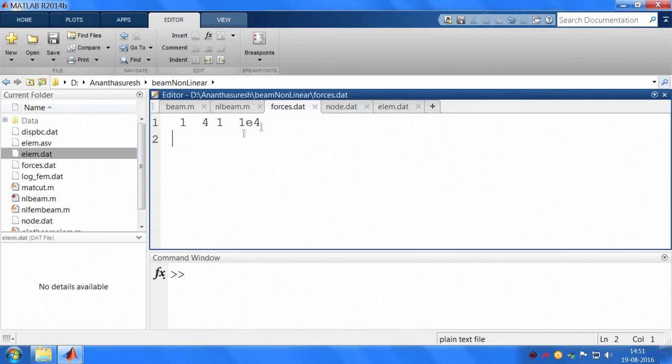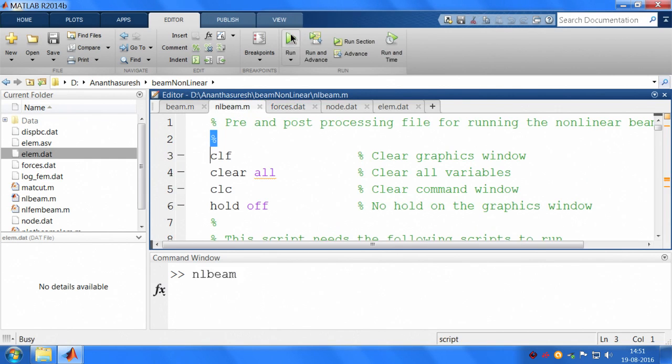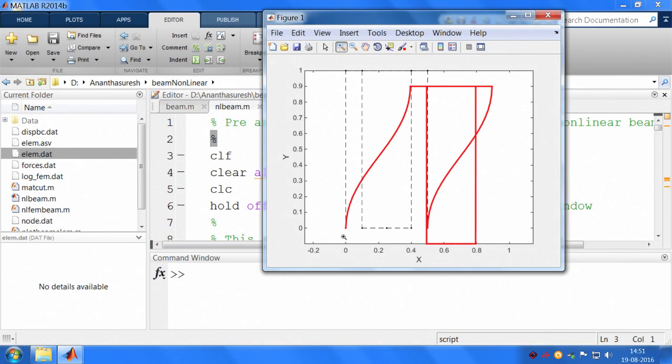If I apply 4, let us run it, let us run the way it is now to see what happens. So, now you see it has deflected, this portion has simply moved like a rigid body, because if you see, now I have added these things, this and this are rigid, I have applied force still at the node 4 in the x direction. So, this has deformed, whereas the other one, this is like a rigid block, to that one we attach the second stage with 2 elastic beams, that moves like a rigid body because there is no force here.